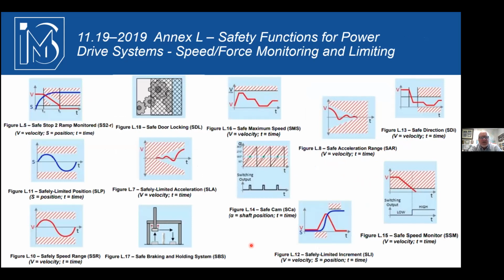You introduce things about not just holding position, but maybe ideas of safe direction, safe positioning, limited speed. Maybe I can go faster or slower, or a combination of direction and speed, of the actuator. So it becomes almost limitless, but there's some pretty cool ways you can get into a safe state that may not be stopped, and it's certainly not going to take a long time to return to normal operation.